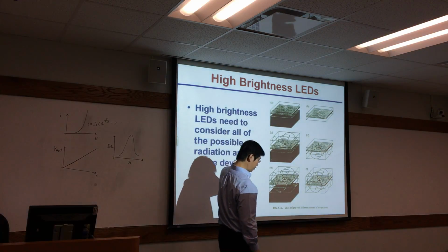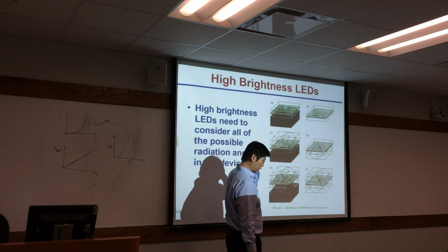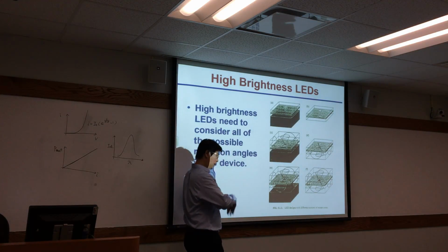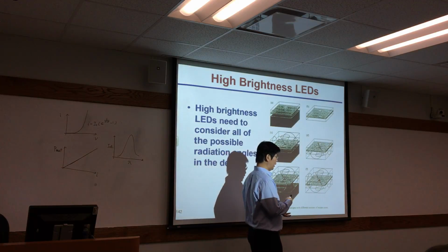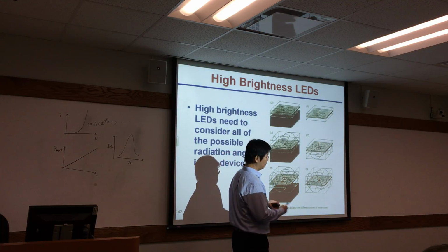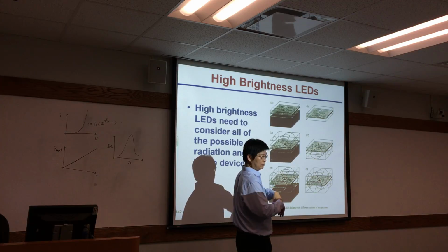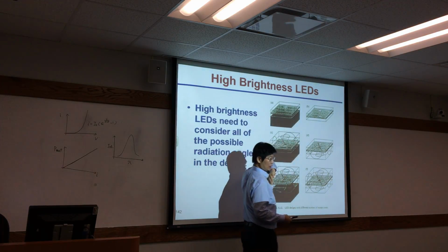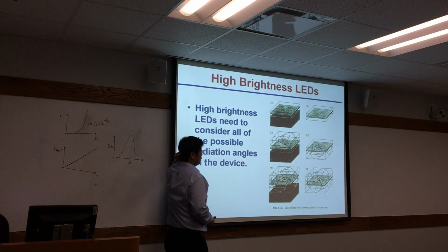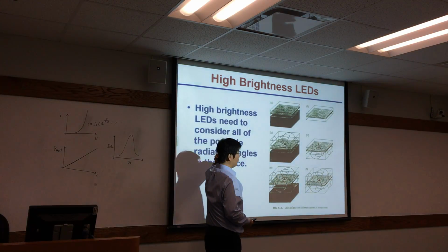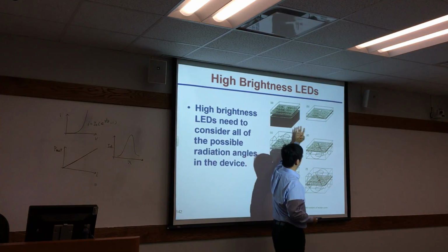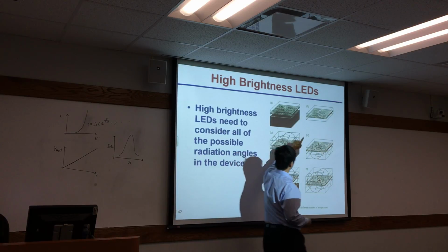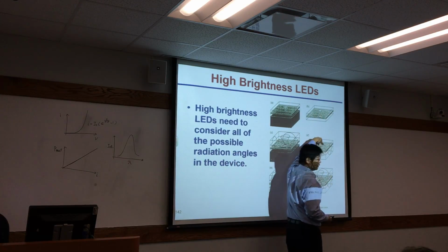So for the LED chip, remember that when we talked about the phosphide system, aluminum gallium phosphide, we use gallium arsenide as the substrate. But gallium arsenide actually emits light in the infrared, which means it will absorb the visible light. So actually that's an absorbing substrate. So how can we handle that? We can remove it, or we can use another kind of transparent substrate, so that we can see the light go up and go down.